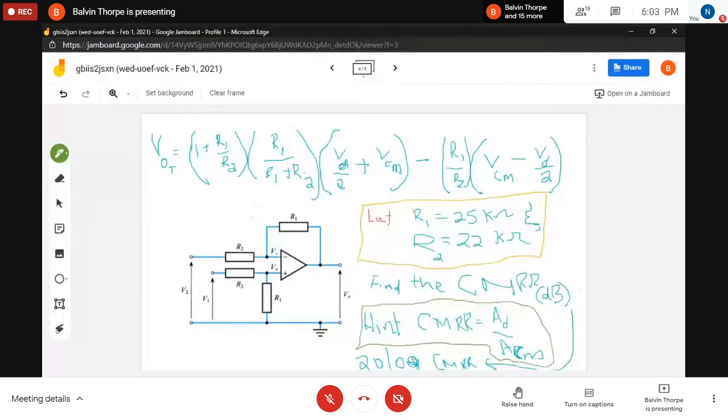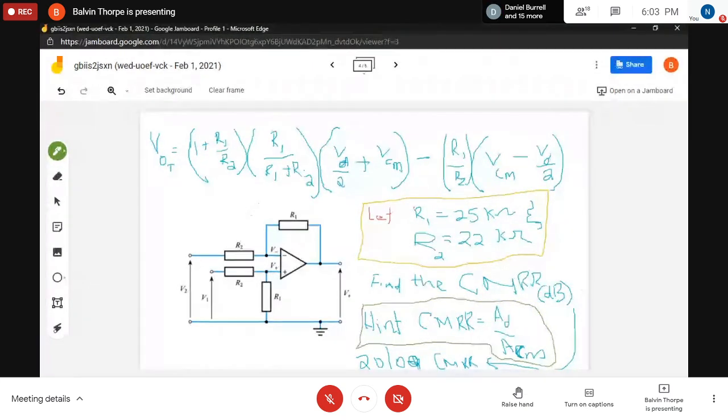Sir, it's a ratio that blocks unwanted signals and lets through the wanted signal. The wanted signal is the differential input signal. It's a number, a ratio that describes how well you would pass through the difference, or block out the noise from the difference of the two signals. All right.